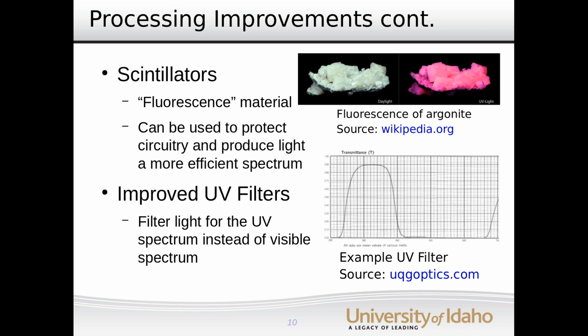One other thing to note is a common passivation layer used is silicon nitride. This tends to be a high reflector of UV light. So there's been work going on in order to make sure that silicon nitride can be able to transmit more UV light and be able to collect more of those photons, so that we can get that image a little bit more accurately and better.